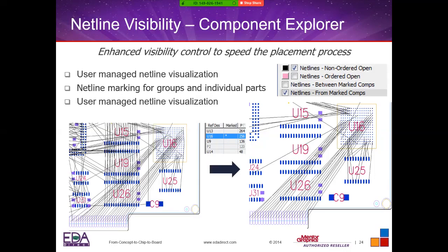So you can mark those nets, and they'll display for you. You also have the ability to zoom in on a certain area. If the rat's nest is within that area, it will stay. If it steps outside, then that will disappear. So this is a good way to minimize your rat's nesting so that you're only working on those nets that you need to visually see.